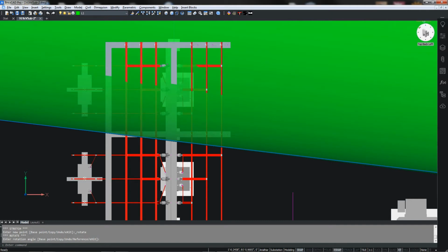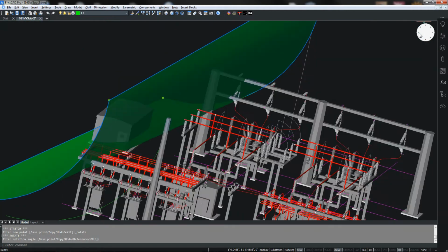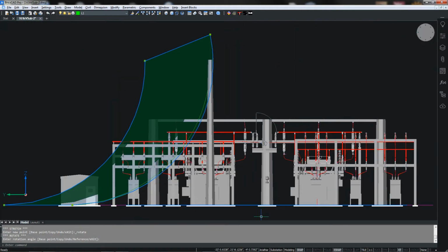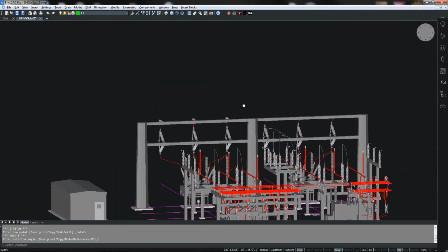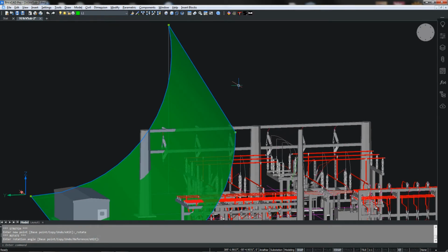So let's go back to the end on view, and again, as you can picture, as the sphere is rolling this way, when it encounters that bus, it will swivel up until it hits this static pole or the static wire up here. So we're going to generate another surface that will simulate that ball rolling and swiveling at the edge of this structure.